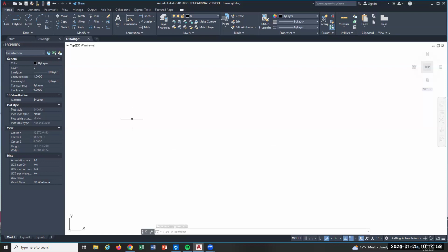So the zoom command, and all commands, you can drive with the keyboard. So you'll find veterans of the software, such as me, we are keyboard drivers, right? If you want to know where the fillet tool is, I probably can't tell you. I don't know, because I just type in fillet and run the software that way. I see it up there now. It's like up there somewhere. Fillet, trim, rotate, mirror, scale. All of those I would type.